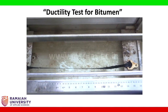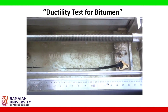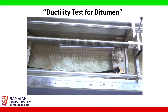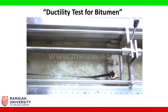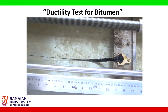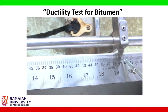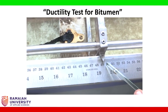Observe, there is a formation of thread and sagging is about to happen. Yes, it touches the bottom. This particular reading, 49 centimeters, is considered as the ductility value of the bitumen.